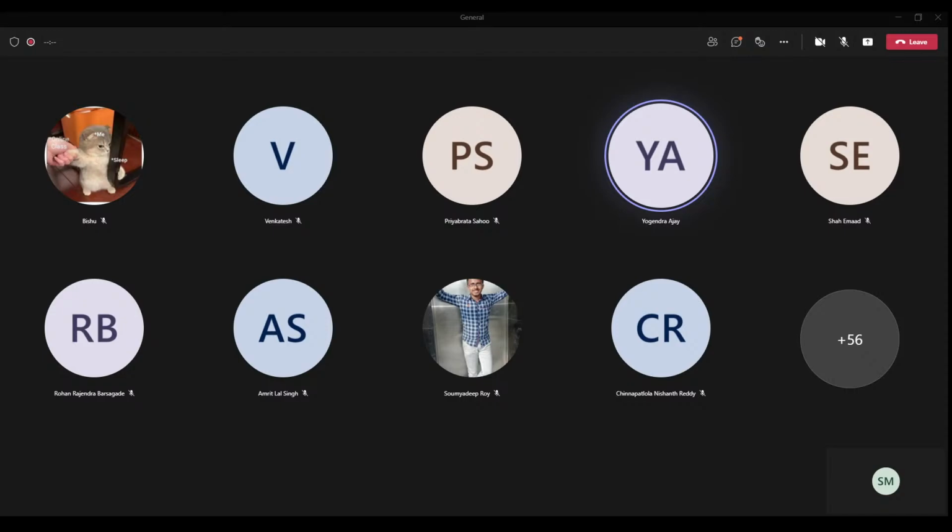The output of the sensor will always be high or low, so the internal circuit should decide whether to output high for this signal. Okay, that is what I wanted to know. Basically, there exist these two types of IR sensors, where a white surface results in high and where it results in low. Yeah, it could be, and it depends on the internal circuitry. Okay.